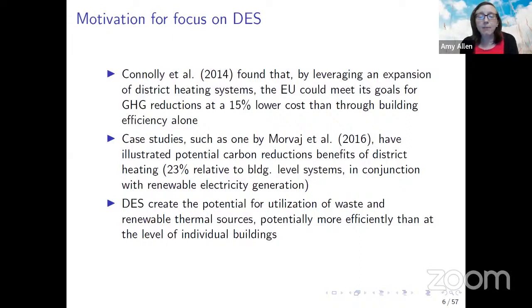And a study by Bufa and others in 2019 found that operating examples of 5G DHC systems in Europe had lower levels of a low density metric, the linear heating power demand density, than typical district heating systems, and then the screening values at which district heating systems would generally be deemed to be cost effective.